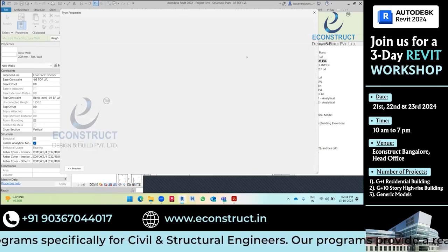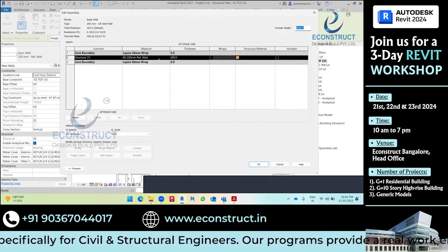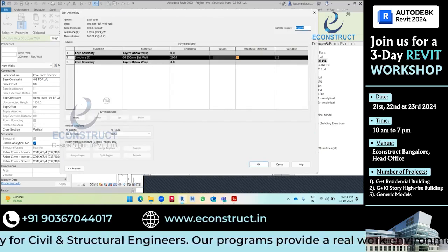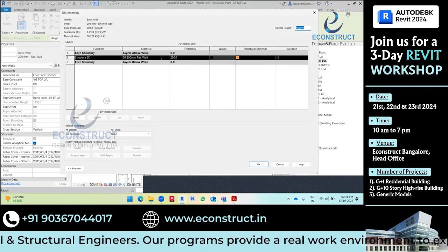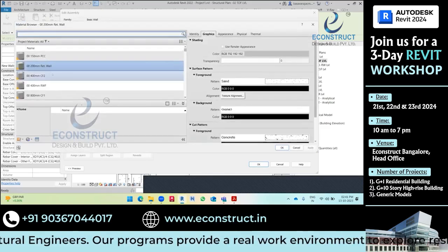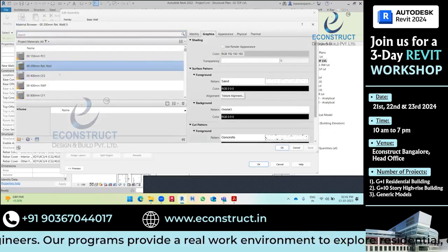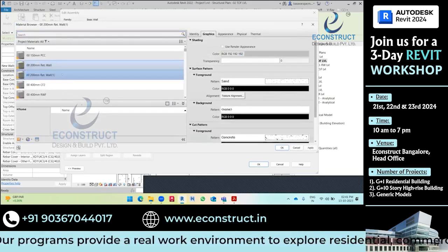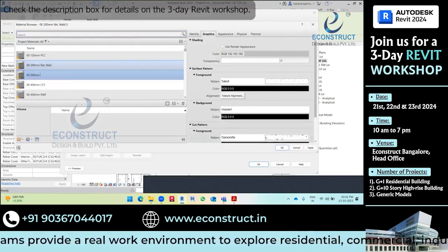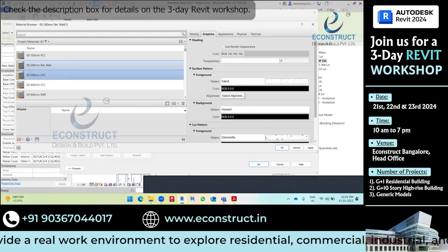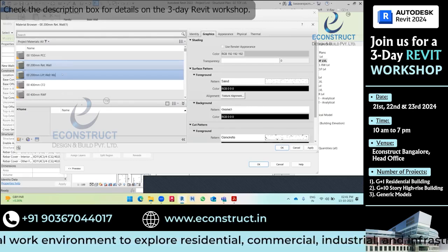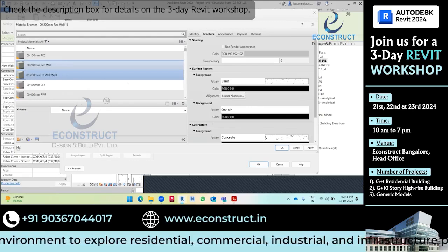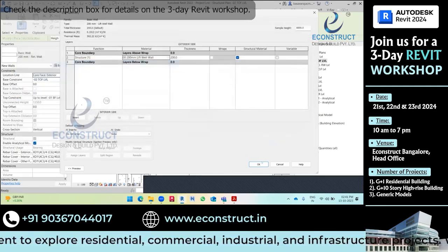Go to edit type, 200 mm thickness, and change the material. Duplicate, lift well wall. Click on apply.